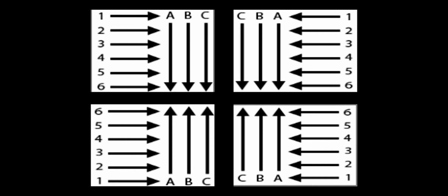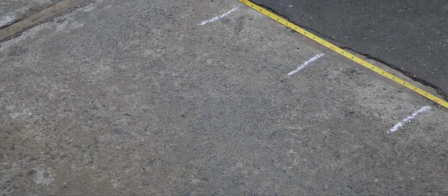It is important that you follow this pattern when surveying, as any divergence from the pattern will cause the data to not match the reality of the site. The numbered lines will be the first axis completed. The second axis, if needed, will use lettered lines.